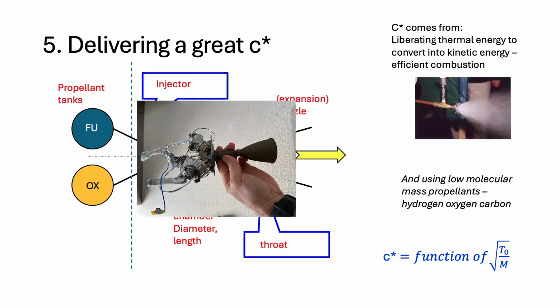But this is what a modern rocket engine looks like. And you can see a large nozzle here. We'll come on to that later. A combustion chamber held by my thumb here. And upstream, there are some valves designed to let propellant in. And what's a bit harder to see is actually the quite sophisticated manifold and injector designed to push propellants efficiently into there and do something really neat, which is cooling the engine.